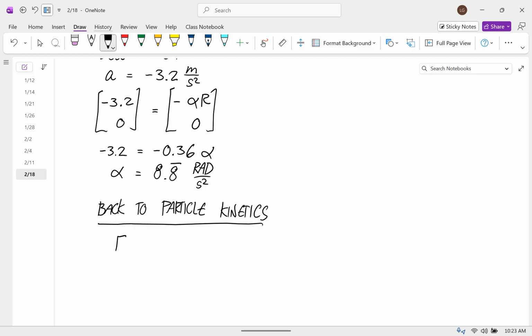Our equation of motion says F net is equal to the mass times the acceleration of the center of mass. And F net means all the forces acting on a body, but remember that all the forces acting on the body are equal to all the field forces acting on the body, plus all the forces acting at the boundary, which is a lucky thing because all the internal forces are a huge quagmire of forces and we can just ignore it. So we should all take a moment to be thankful about that.